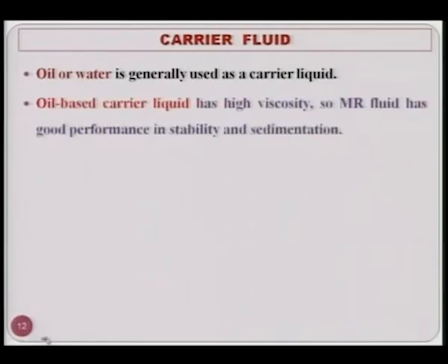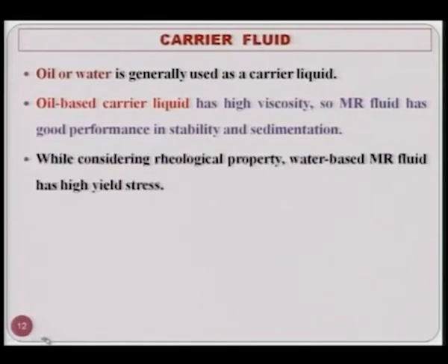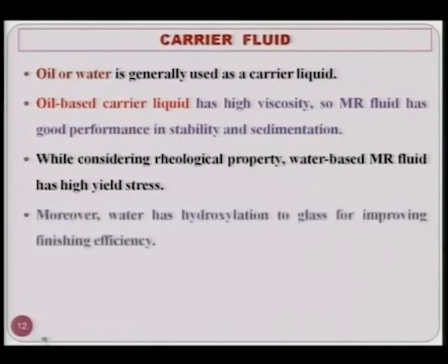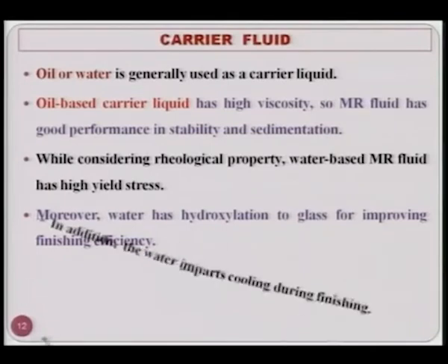Oil based carrier liquid has high viscosity, so MR fluid has good performance in stability and sedimentation. While considering rheological property, water based MR fluid has high yield stress. Moreover, water has hydroxylation to glass for improving finishing efficiency.